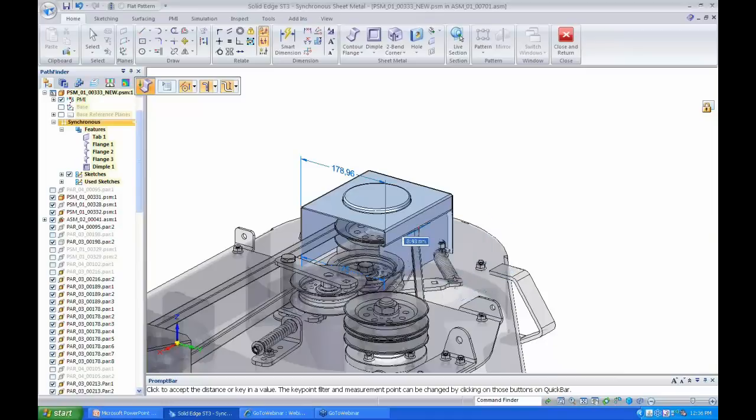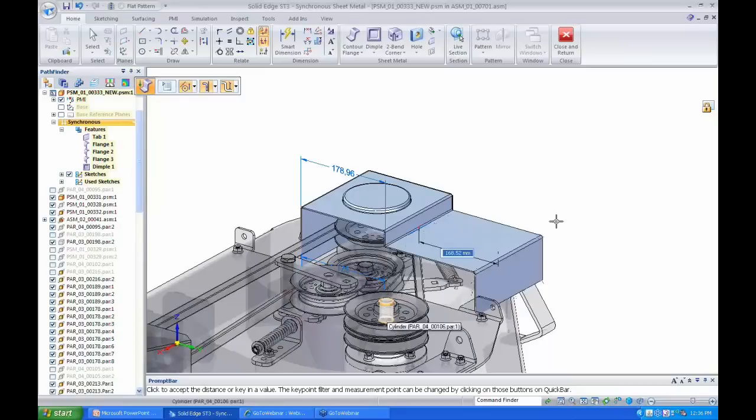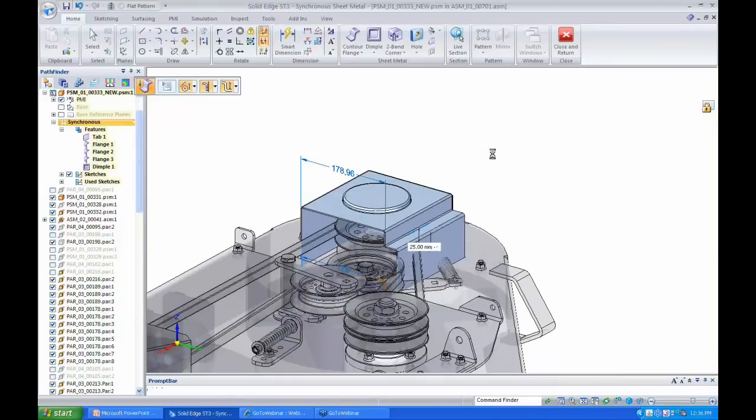So if I keep my cursor on the background assembly, you'll see that it tries to snap all the time, and I've seen a lot of times it gives us a small alert that it cannot place or something like that. So it's always better if you know what your extent is going to be. It's always a good practice to keep your cursor on the white space, so that you can define the extent without snapping into any background point of the assembly. So in this case, it's going to be 25 millimeters.